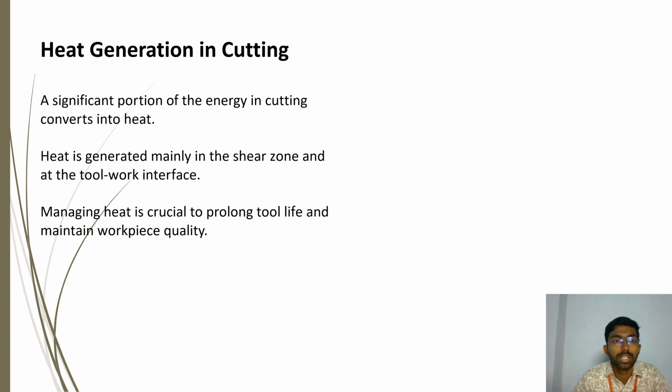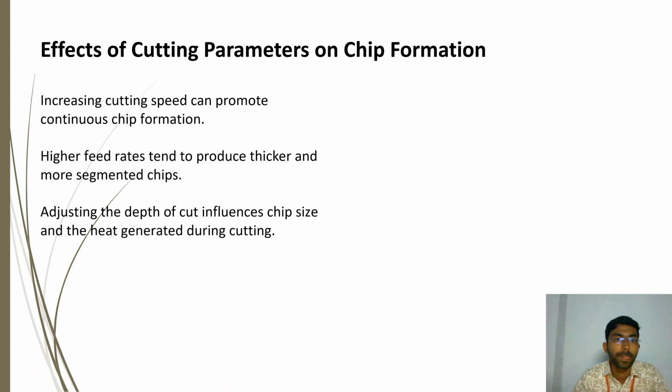Heat generation in cutting. A significant portion of the energy in cutting converts into heat. Heat is generated mainly in the shear zone and at the tool work interface. Managing heat is crucial to prolong tool life and maintain workpiece quality.